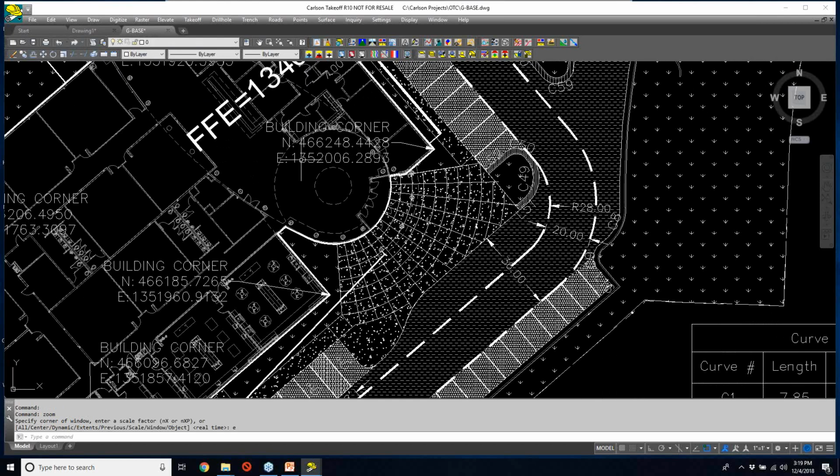And before we do that, one of the things that I'd like to do is potentially get rid of some of all this extra hatching and stuff that's in here, because that's just sort of clouding up our drawing, if you will, and it's sort of slowing things down. Because that hatch is all intertwined with other parts of the map, and we can always get it back if we need to by simply re-importing the PDF, or maybe we can just freeze it.